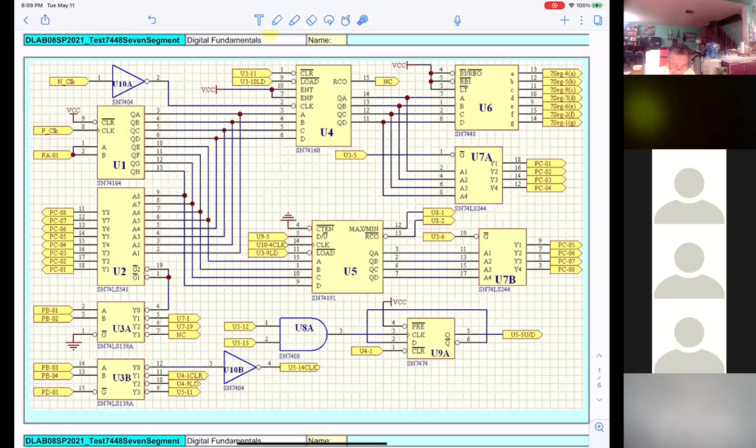After you count up, done. So you get the two outputs here, go into the AND gate here, and apply the clock to U9A. It will toggle. Now it will be 1, and it will count down automatically. So once it hits the top, it will automatically switch to counting down. Exactly. So you don't have to reset it to count.